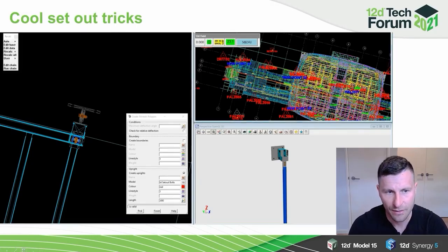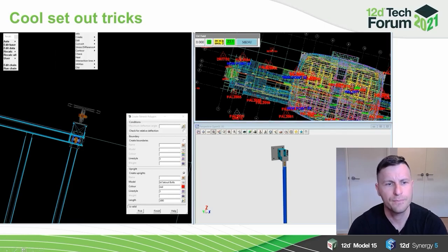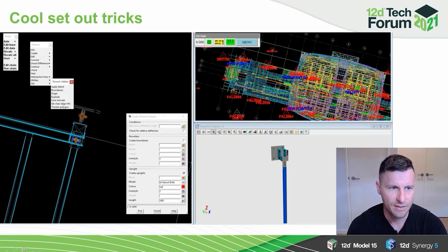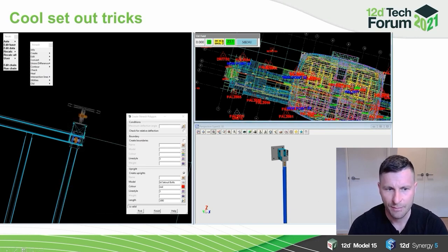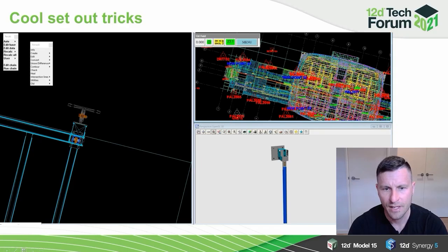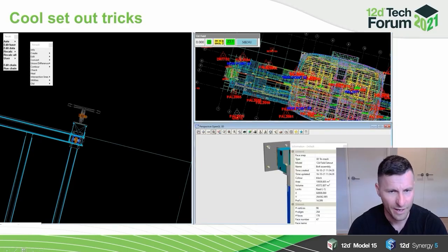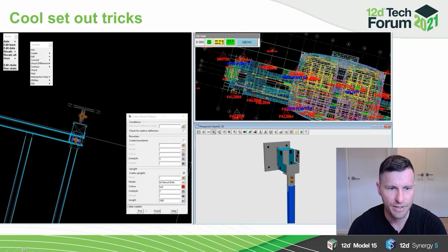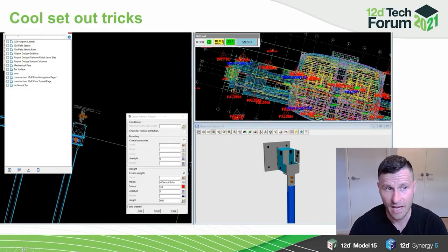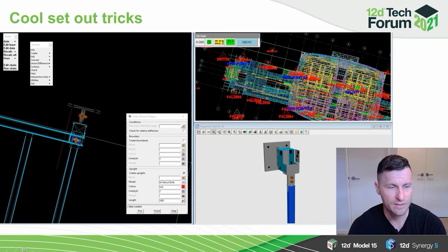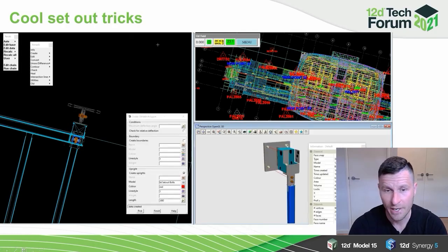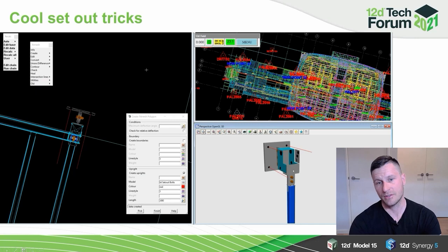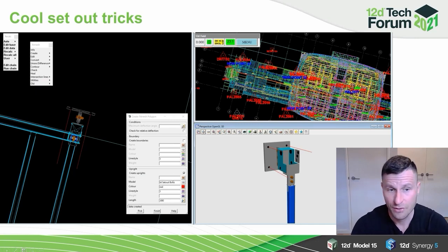So I'll select the create tri-mesh polygon from the utilities at the bottom there. That's it there. With this, it gives you the ability to give what they call leaders. So that's basically the centroid from that face, and create lines. As you can see on the screen there, it will dynamically create the lines for the center. That enables us to set out the bolts when we only have the 3D digital information, such as we do in this scenario. And so it's quite easy to create them.